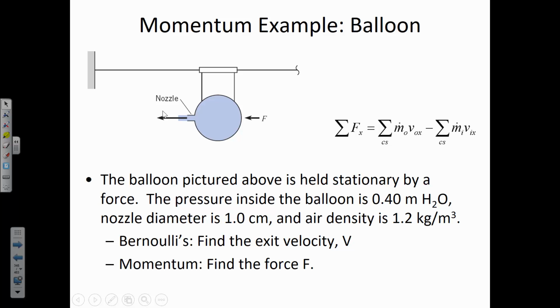Equivalent to the depth. Yeah, so the pressure here, let's call that 1. So the pressure at 1 is the same as the pressure would be in some tank where you have a depth of 0.4 meters and the tank is 9810 newtons per meter cubed. So it's water. And so it's just basically saying apply the hydrostatic equation and you can know what the pressure at location 1 is.